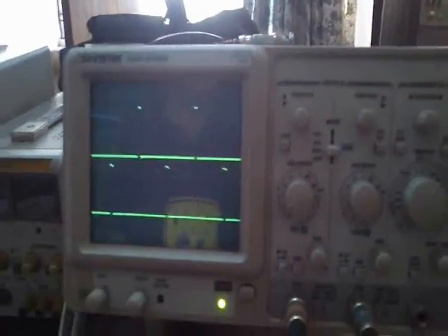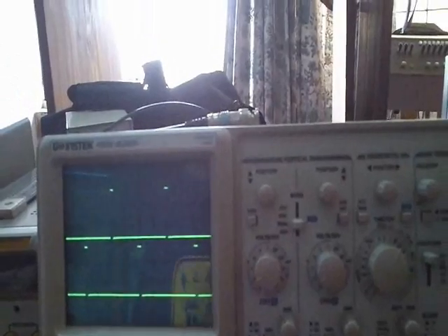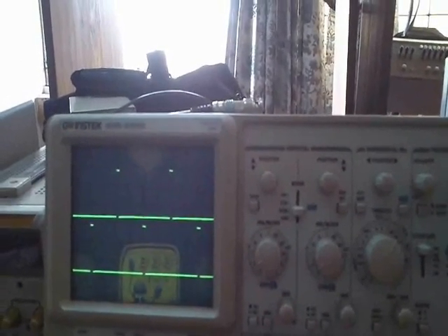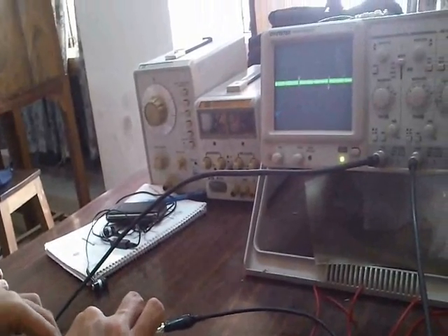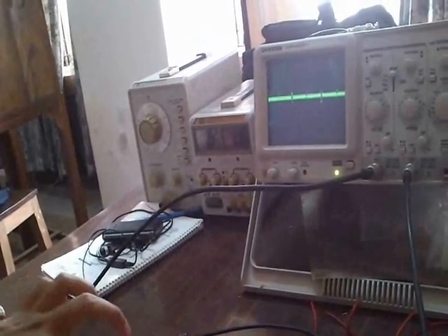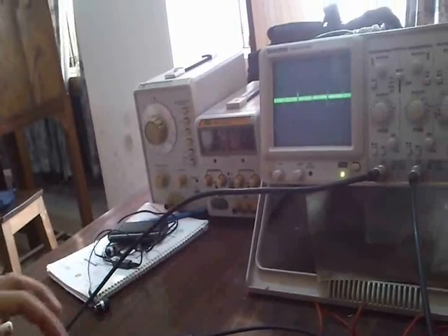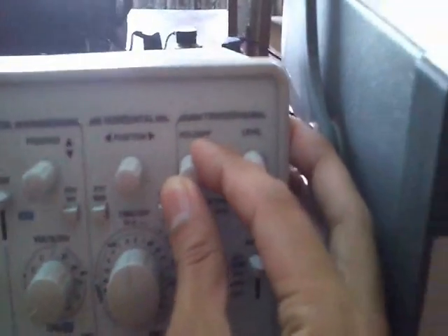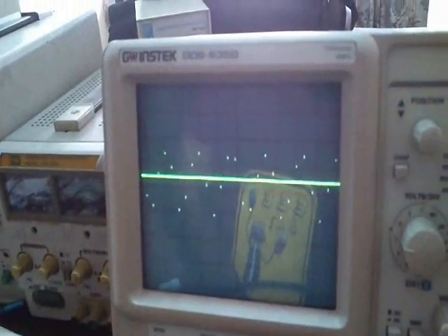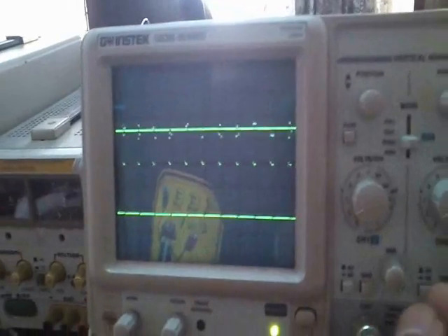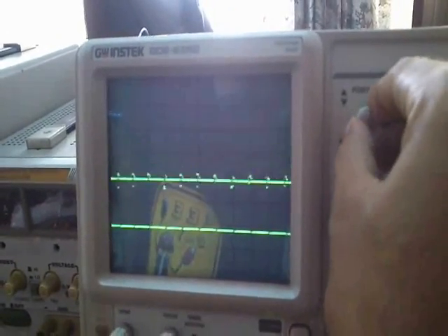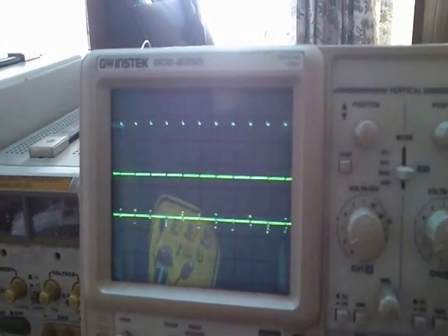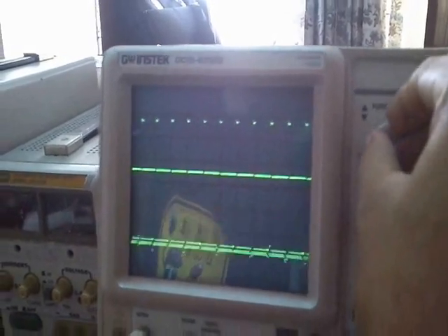We use it to sample our input signal. Now we can see the sampled signal of our main sine wave. We do it by multiplying the main signal with the shifted clock for both cases. We use the AD633 IC for multiplying purposes. Now we see the clock signals above and the corresponding sampled signal.